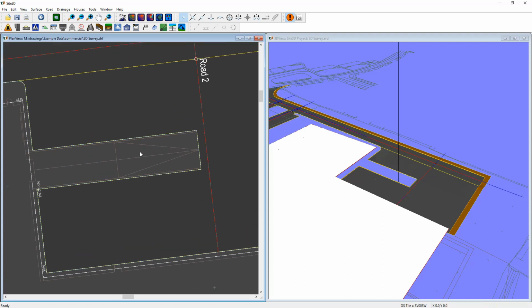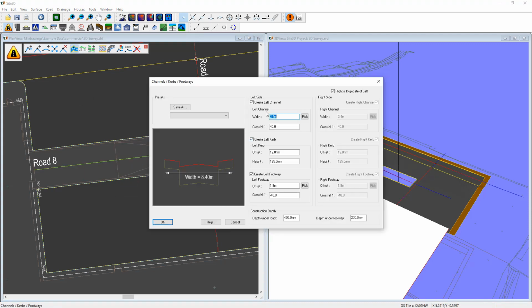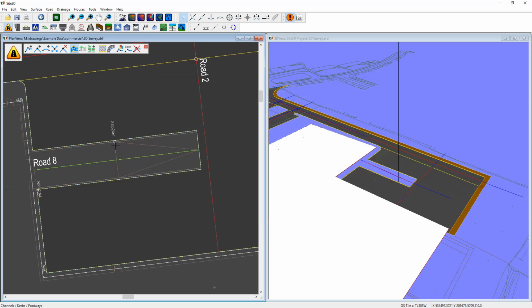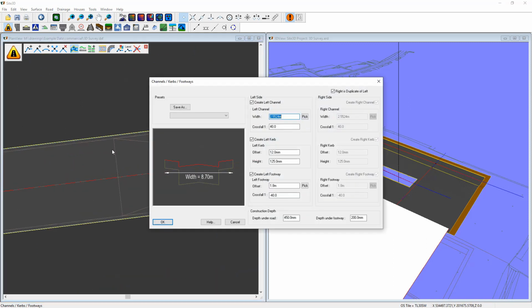So this allows me then to put in a new centerline where the road used to be, from here to here. And I can specify the width of that to be the width of what I need it to be, so to the inside here. And I can say, well, I don't need any curbs on that, but I do want this to be something like 1 in 150 to 1 in minus 150. So there's a bit of a cross grade to it, whatever.